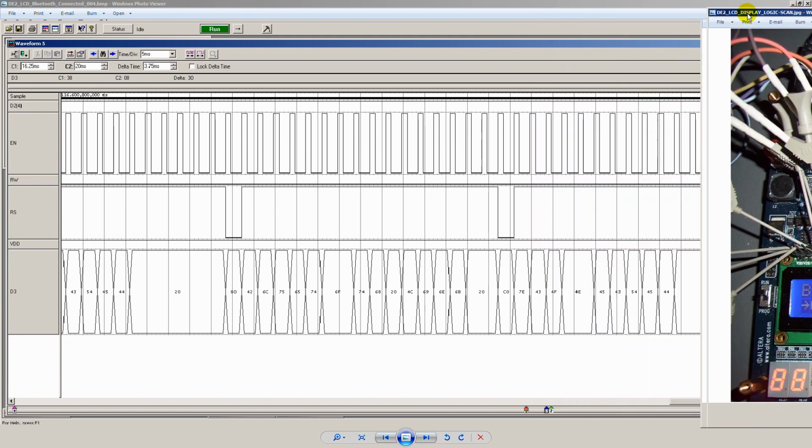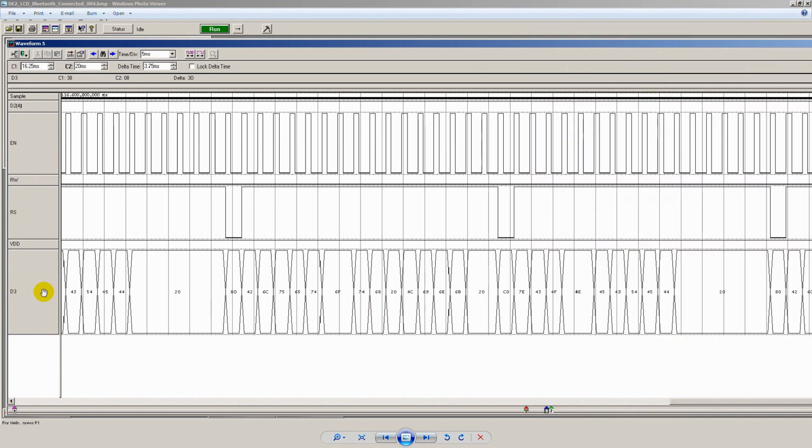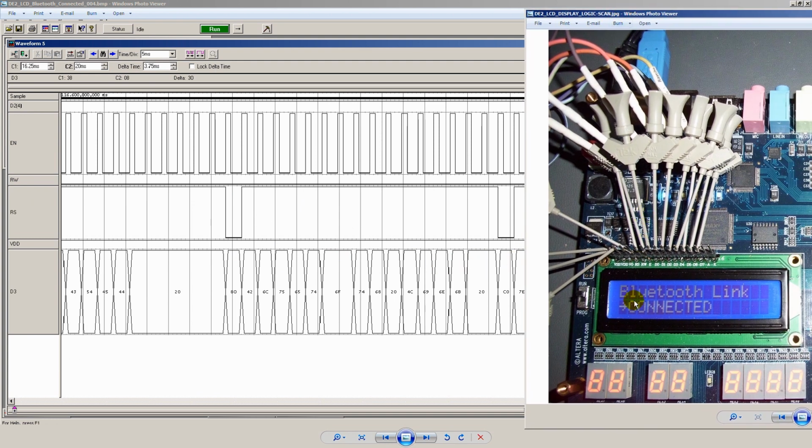And now what that means is that it's essentially monitoring the data bus here. And so if we were to go in somehow and manipulate our signal lines or variables, if you will, that are holding the information for specific characters when our RS value is high, if we could manipulate these at different points, we would essentially be able to change the characters that are being shown on the screen. And so essentially that's exactly what I've done.